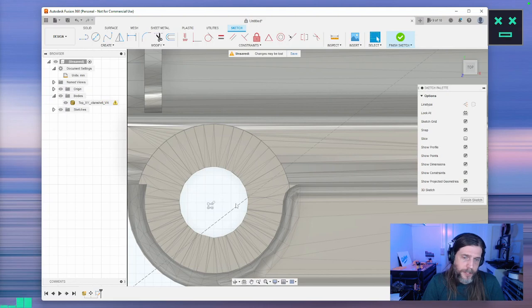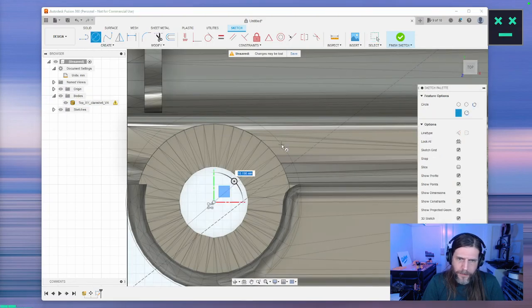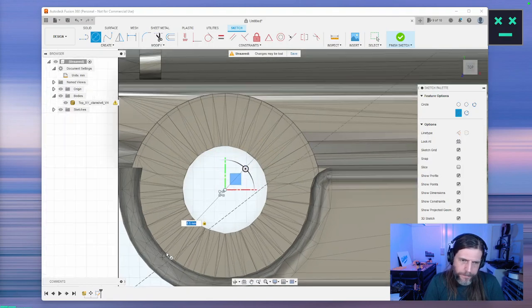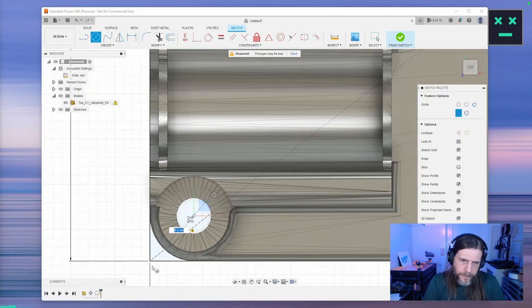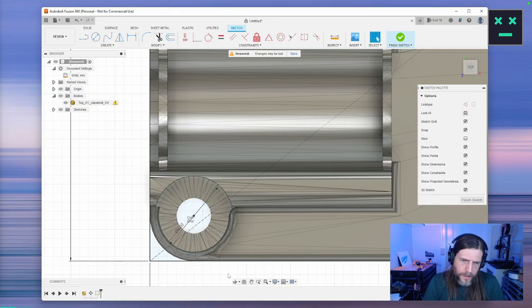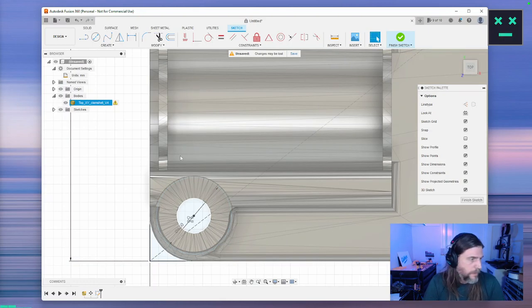The inner diameter is based on a screw clearance hole, so we'll do that as a hole later. For this, though, what do we think this is? What was the logic that went into this? Looks sadly kind of arbitrary. My inclination would be to make it a little bit smaller, because I don't like the way in the current print that it eats into the wall of this dude where the bearing goes.